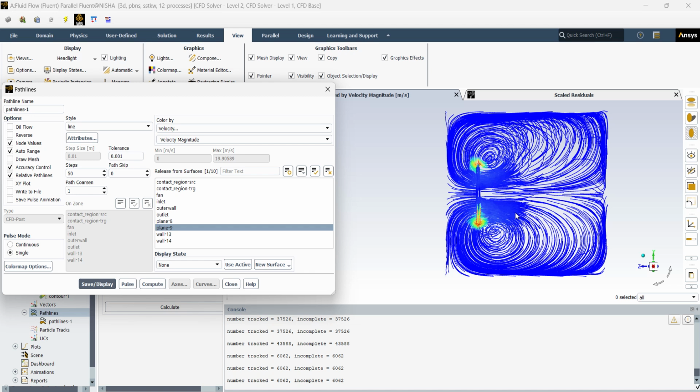Now if I run at any horizontal plane, if you create, for example, on the floor at maybe 20% of the height, 50% of the height, and all, you can get different velocity contours, velocity, pressure, a bit varied, if it is fully run. And here I have taken everything as a wall, top also wall, bottom also wall, side also wall. That's why the flow is confined within this boundary.